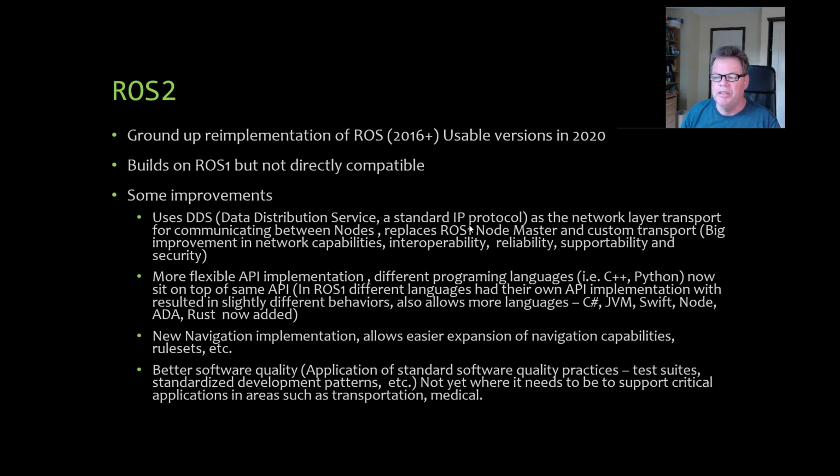By using this data distribution service, there's some big improvements. Things like now has a lot more interoperability, so you can even use DDS compliant components that aren't ROS2 components, and because DDS is a standard protocol, it's used in things other than just ROS as well. It's got improved interoperability. Again, it's a standard protocol, follows lots of standards, so is better for getting things working together.